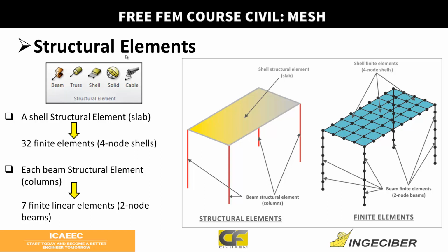Usually, if you want to perform a code checking, mostly a linear structural analysis, a global analysis, it's very accurate to use beams. If you want to change your section and maybe one dimension, that's very easy and fast. The beam structural elements have bending stiffness. If you want to take into account the bending stiffness, beams are the best option.